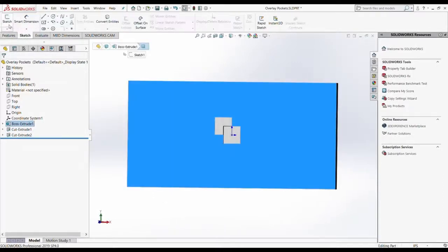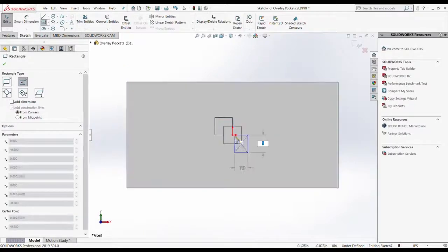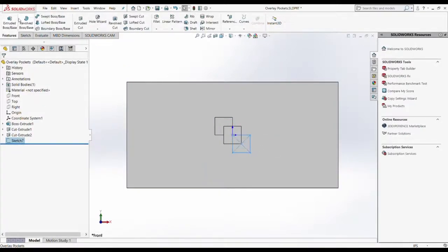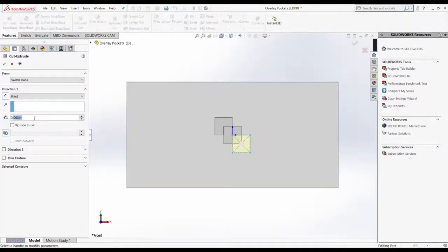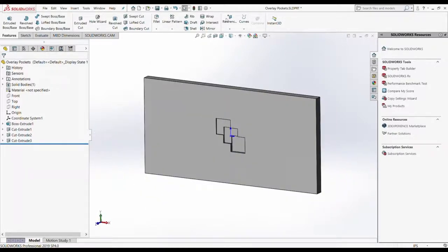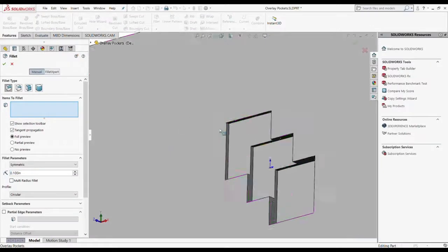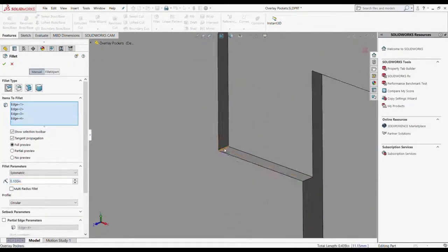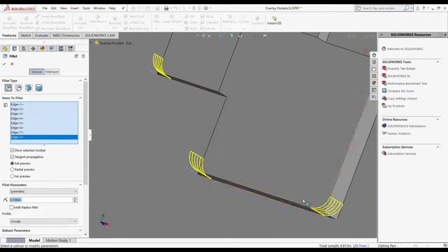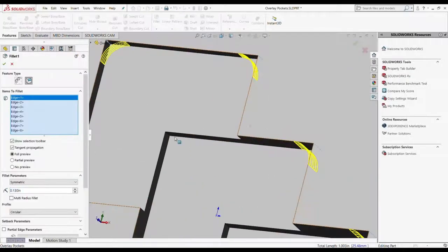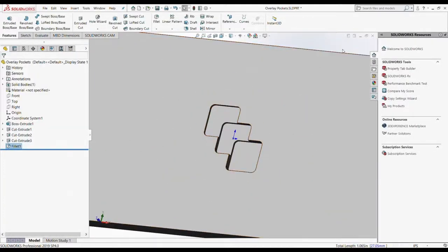The next step after this will be to generate a CAM toolpath. We've used both Solidworks CAM and the Autodesk HSM Works package to generate G-code for our models with good success. Today I'm going to use Solidworks CAM just to keep it simple. And while this isn't a tutorial on how to use either of those CAM solutions, it's worth mentioning that the general flow is that you need to configure the CAM to give some basics about how the piece will be oriented in the machine and what commands should be generated, including the speeds and feeds.